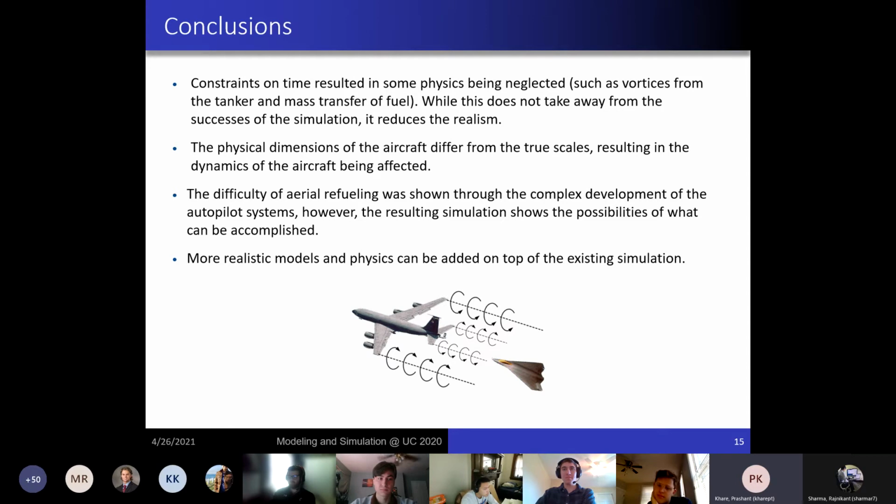In general, if you want to mimic the physics which might happen because of the size, shape, velocities, whatnot, one of the things which you can leverage from your fluid dynamics courses is the concept of dynamic similarity. So for example, Reynolds number, if you basically choose your forces based on what expected Reynolds number might be, that might give you a much closer solution than actually thinking of doing the real scale things, right? So that's sort of the usefulness of some of those things that you've studied in your classes. But other than that, good job.